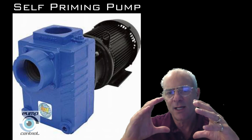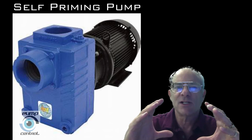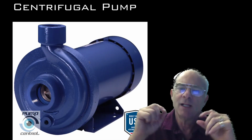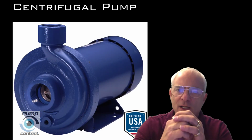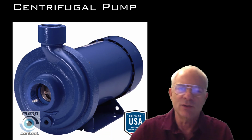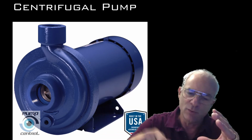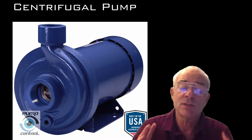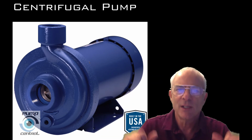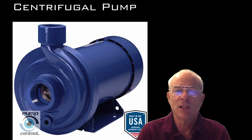Whereas if it's a more efficient but not self-priming volute, you run the risk of the air getting airlocked in there. And what you have to do is turn the system off and bleed the air out and refill it with water, and it's a big hassle. So thus the whole genre of self-priming pumps.